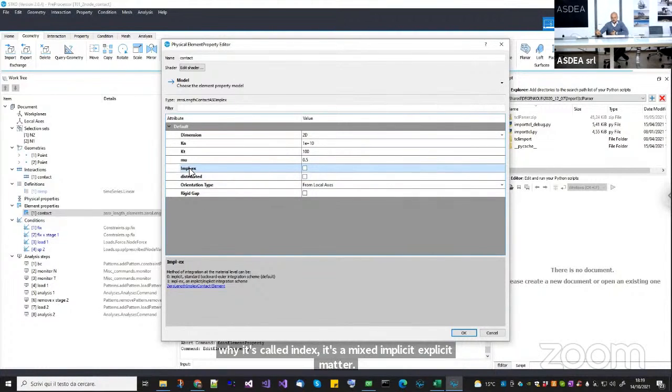The same rules that I've explained for the damaged TC model apply here. So if you use the implex, the model will converge much better. It will be much faster, but the time step should be smaller. And I will show you in some examples.